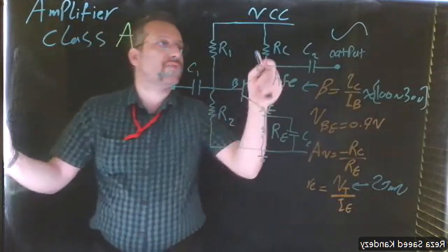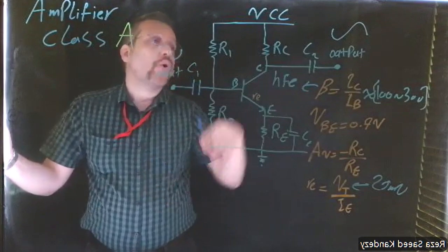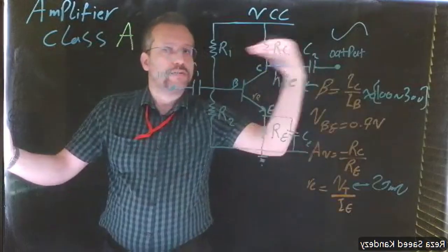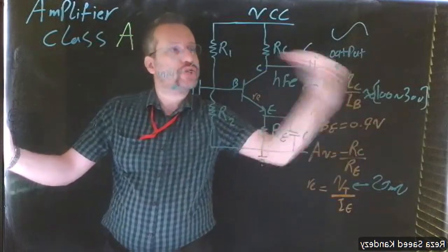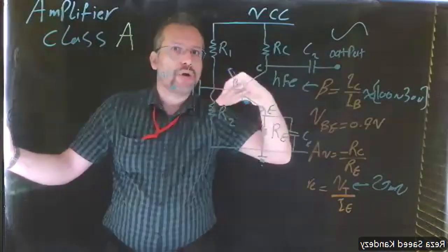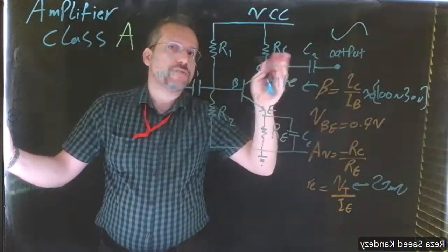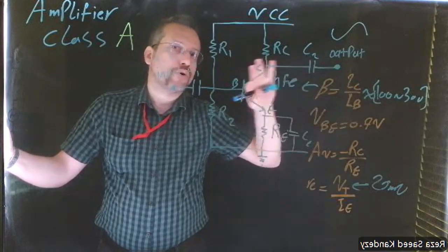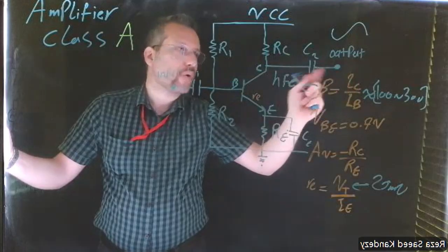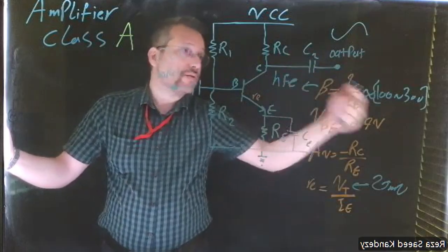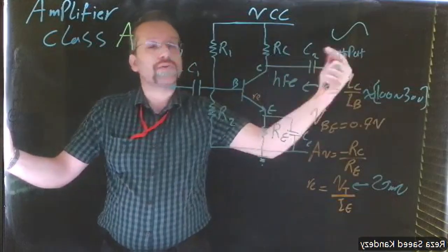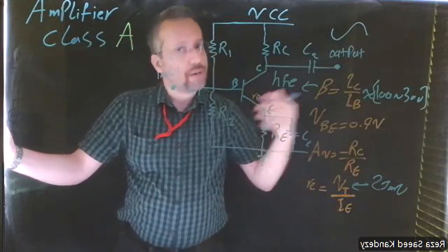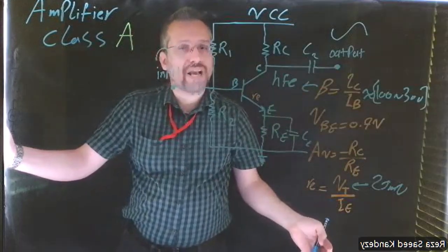Sometimes you want a specific voltage at the output, or sometimes you want a specific impedance watching the whole system from the output, for impedance matching for maximum power transfer. Sometimes the output impedance is what matters, and sometimes you need the gain to be a specific value.